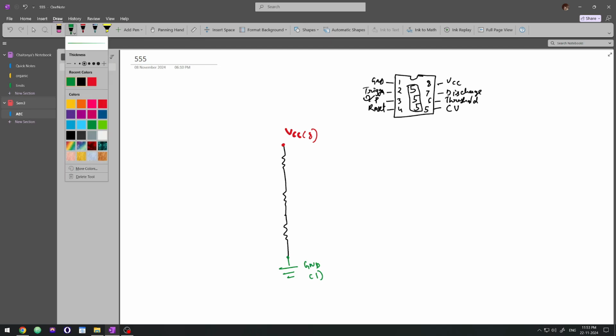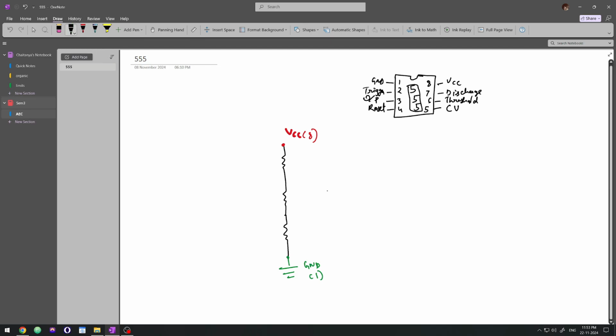Okay, now let's get into the rest of it. Now we're gonna have 2 comparators, op amps. So one comparator here and one comparator here. Non-inverting terminal, inverting, non-inverting, inverting. Okay, now let's start from the below one. So here, first of all, let's write this 5k, 5k and 5k. So down here, the inverting terminal of the lower comparator, and this is the upper comparator.